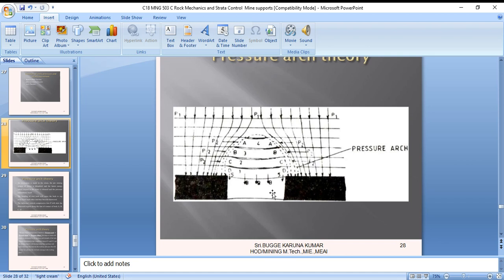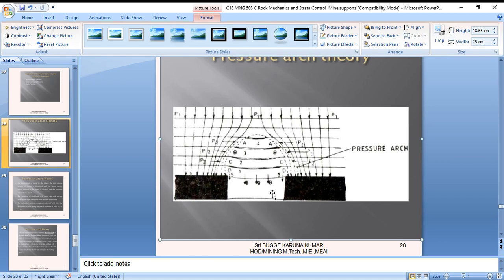The sag and separation of the immediate roof are reduced or eliminated when the roof bolts are tightened and hung from the self-supporting main roof. The loading carried by the roof bolt due to the suspension can be determined easily.